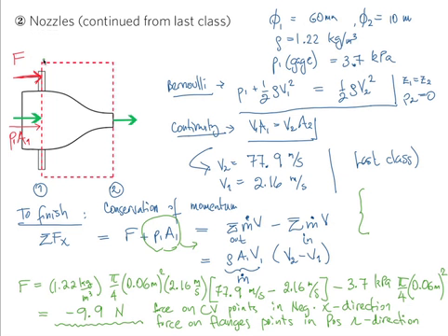That box is cutting through the flanges through the middle. All right, so basically the box has one side of the flanges in it and the other side out of it, right? So the only source for that force is the fact that there are bolts holding the flanges together, right? There's a force on the control volume, on this box that I've drawn, that points in the negative direction, so that because this is not moving, there has to be an equal and opposite reaction on the outside world.